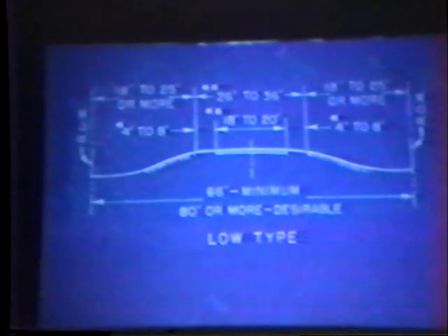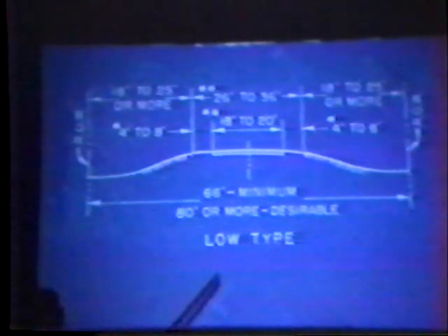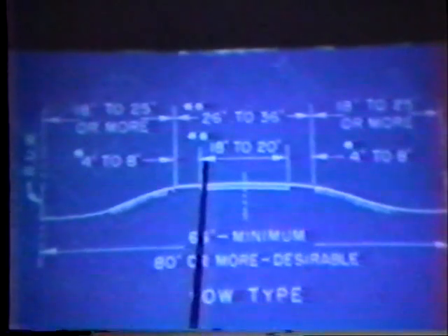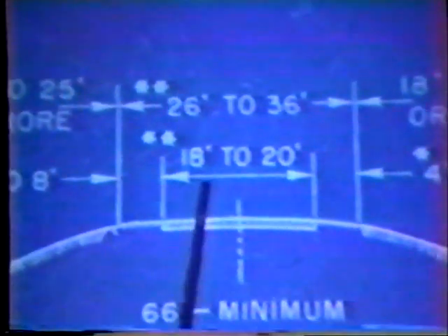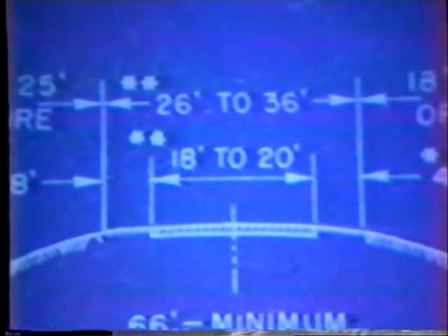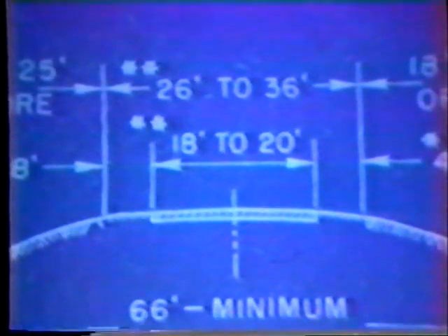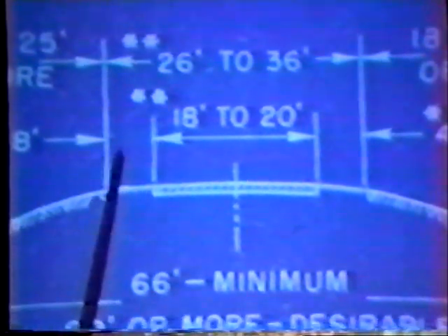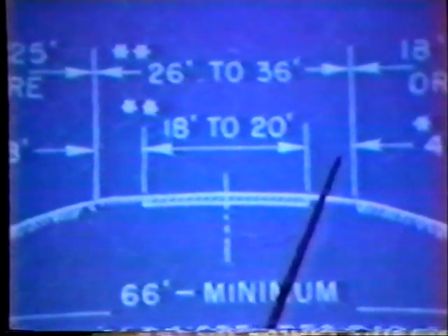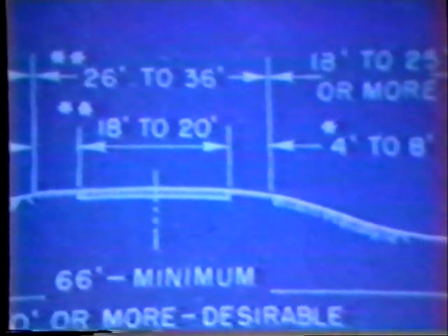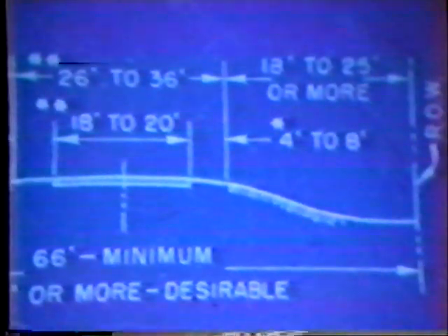Let's define what we're talking about here in terms of various types of highways. I think the slide that didn't drop was the slide that said we were shifting gears from talking capacity to talking geometrics. Anyway, in terms of design standard, we're probably talking anywhere, let's say, 16 to 20 feet of a paved or central surface, with maybe desirably 5-foot shoulders, maybe anywhere in the range of 4 to 8 alongside the road.